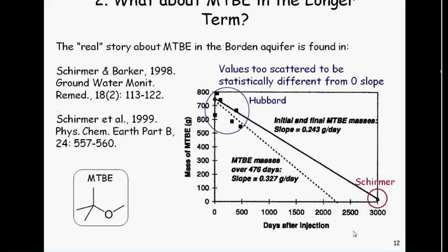So the degradation needed to get rid of that chemical requires a lot more than what normally occurs at field sites. Remember, MTBE is very soluble, so it's often present at the source in milligram per liter quantities, and people were trying to get it down to 10 micrograms per liter, many orders of magnitude reduction in concentration. That would require a very good biological process as well as dispersion to do it.